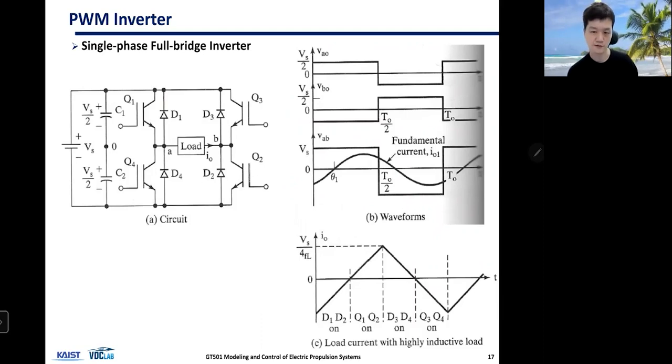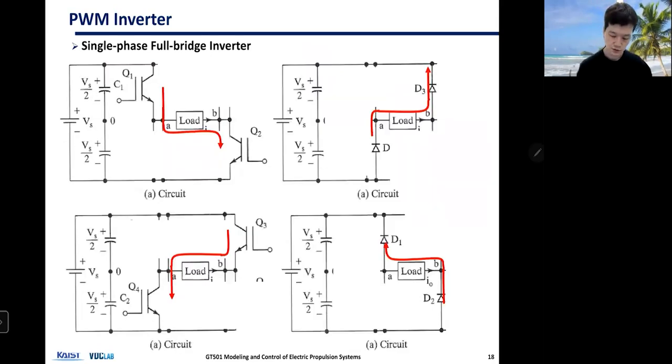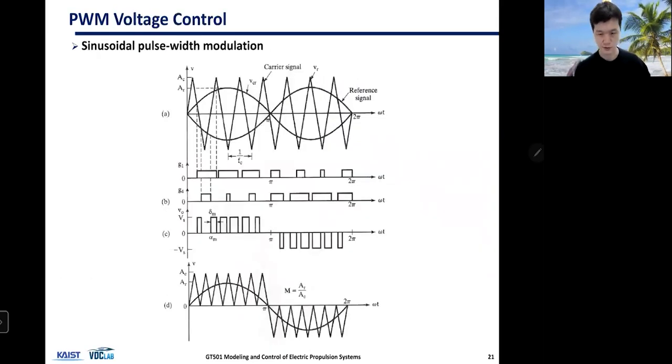Ideally, in order to generate maximum torque and maximum efficiency, we want to be able to provide a sinusoidal AC signal. But to do that, you need to control the pulse width to generate a sinusoidal signal. So in reality, you need these techniques to be able to create this smooth sinusoidal three-phase AC voltage and currents.